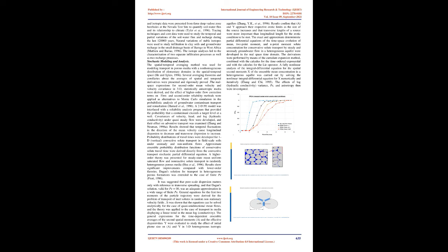Dagan's solution for transport in heterogeneous porous formations was extended to the case of finite Pe, Fiori, 1996. It was suggested that pore-scale dispersion matters only with reference to transverse spreading, and that Dagan's solution, valid for Pe equals infinity, was an adequate approximation in a wide range of finite Pe.